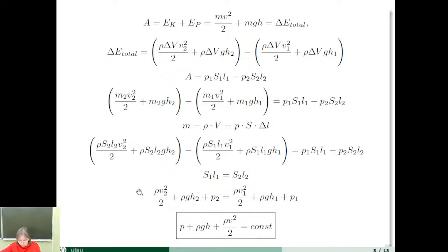According to Bernoulli's law, the pressure in the flow is higher where speed is lower, and vice versa. For steady irrotational flow, the velocity, pressure, and elevation of an incompressible non-viscous fluid are related by an equation in a box.